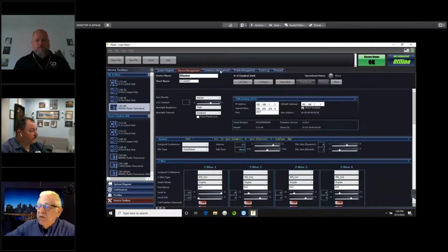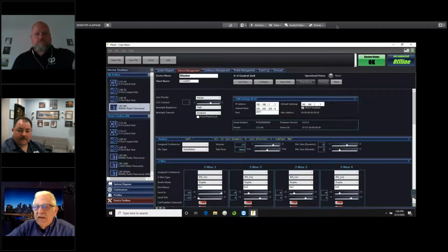And by the same token, if that 2-channel RTS, the TW line basically comes in on one XLR, you'd Y connect it to the 2 inputs with a regular Y cable. So correct. For channel 1, you'd select RTS channel 1 to get ClearCom channel 1 out. And the only difference is it would be 10 dB down from your normal RTS connection.